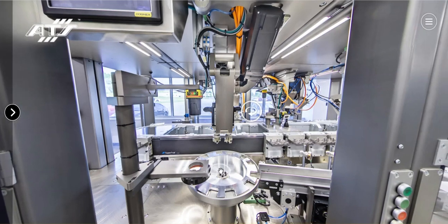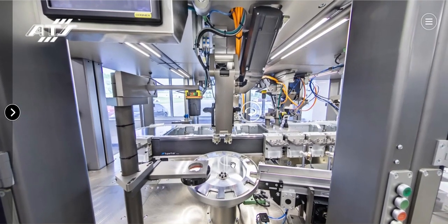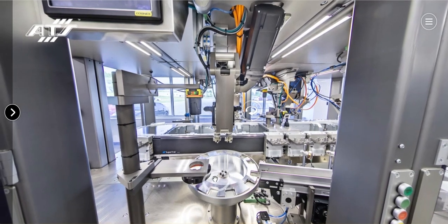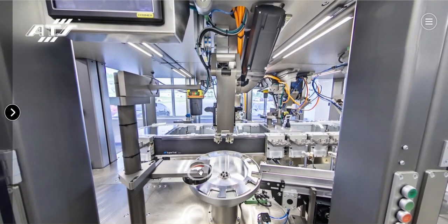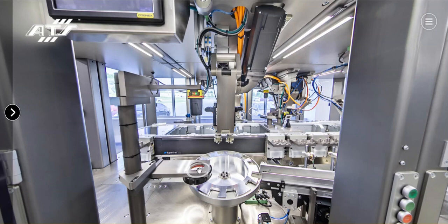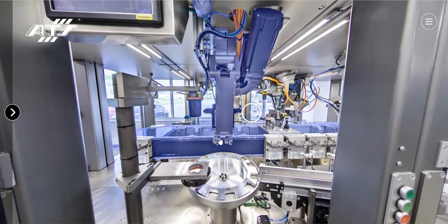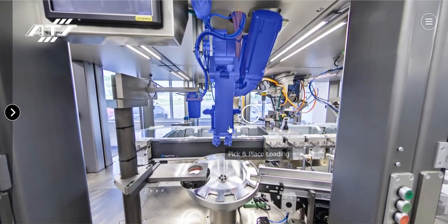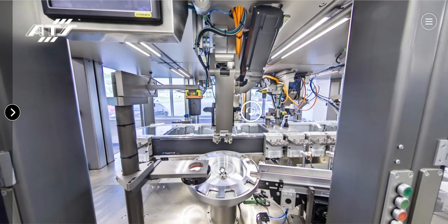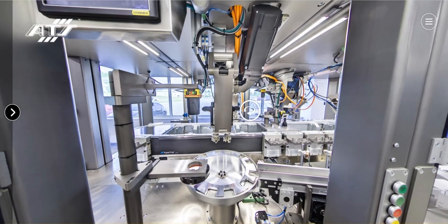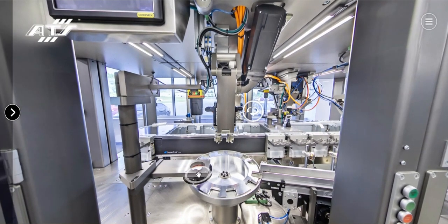The disk is on a rotary servo, so the disk is rotated progressively around such that each part is presented to this camera. The camera takes a picture of the part, determining what radial orientation the part has to be in, because one of the characteristics of Symphony is it can do both high-speed pick and placing and radial orientation at the same time. So we capture parts into the disk, we check their orientation with a camera.